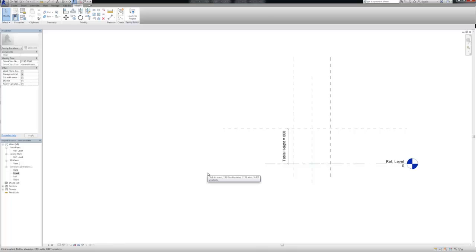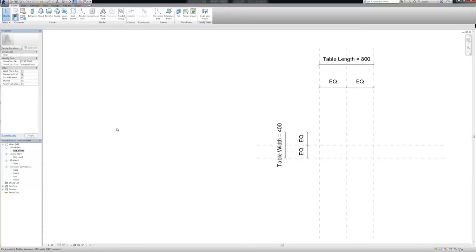We are now ready to add forms to our components. We can add solid forms or void forms. We can use any of the form generation methods. To make these forms dynamic and resizable, we will use the reference planes to define the key aspects of the geometry. That way, when a reference plane is moved, the form will be resized. Now let's see how that works.